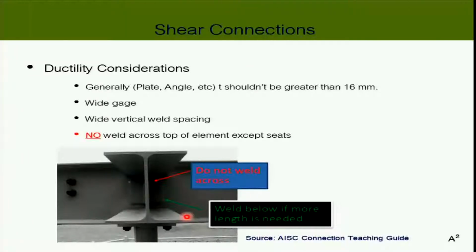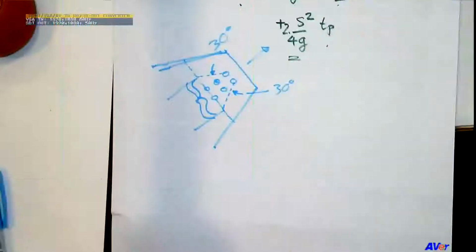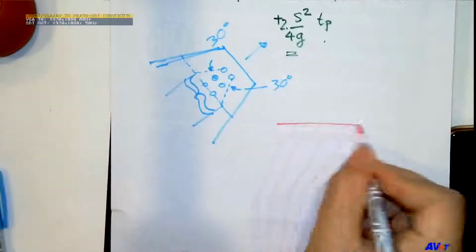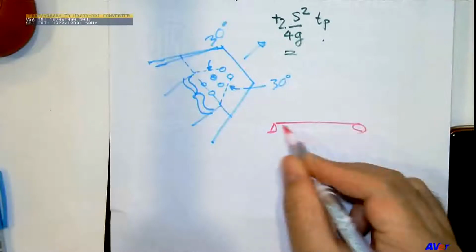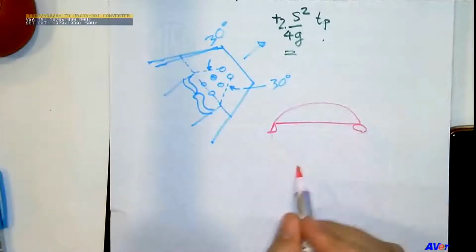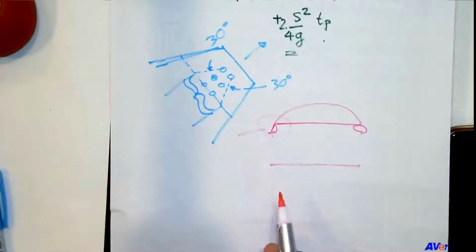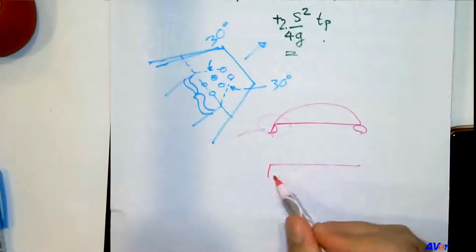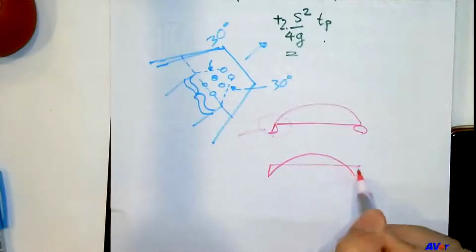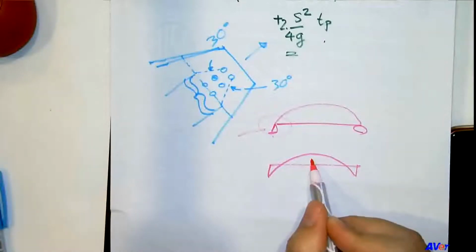Because, from the beam point of view, if you have a simple beam like this, let's say the bending moment diagram is like that. And if you provide a detail that is not really a hinge or roller, moment will occur here. So that means the overall moment of the beam will be reduced, right?